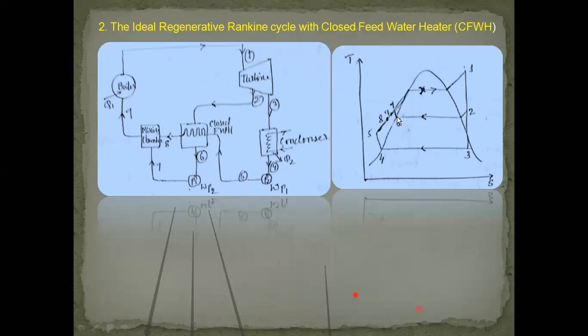This is a point. Again, it is pumped with W2 from 6 to 7. So 7 is the condition of this steam after passing through this closed feed water heater and the pump. This is the condition 7 for the steam. This 5 goes out at 8. So 8 and 7 get mixed up in the chamber, and the resulting point is at 9.